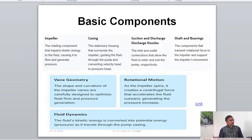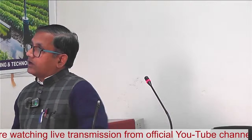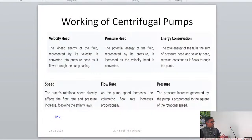So on the technical side there are three types of heads. One is the velocity head, another is the pressure head, and that will define the energy conservation. Velocity head means the kinetic energy, which the fluid represents as velocity and converts into the pressure head, because all engineering concepts work on the law of energy conservation. Energy can neither be created nor destroyed, it always remains the same. If some part of energy is converted into another head, the same concept applies here.